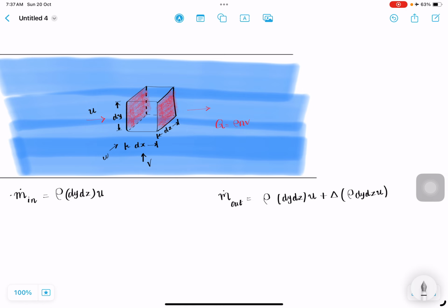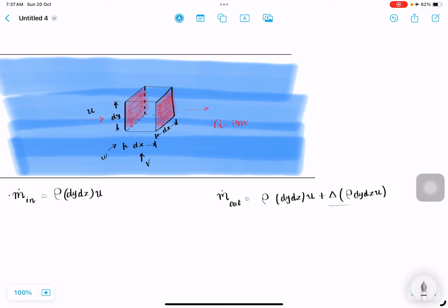And you could see that the fluid is gaining some mass. How it gains, we will see that a little later, but assume that the fluid is gaining some mass. If that is the case, it is gaining some mass along the x direction. So what I will do is I will just multiply and divide by del x. I'm not going to do any damage to this equation. Mathematicians will not allow us to do it this way, but simply I'm multiplying and dividing by del x.